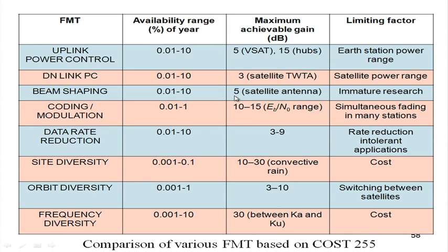You don't touch the power amplifier. In that process you save on intermodulation products and adjacent channel interference, but your problem is that the satellite antenna becomes very complex. Normally these are designed as complex array antennas with additional phase and amplitude adjustment.